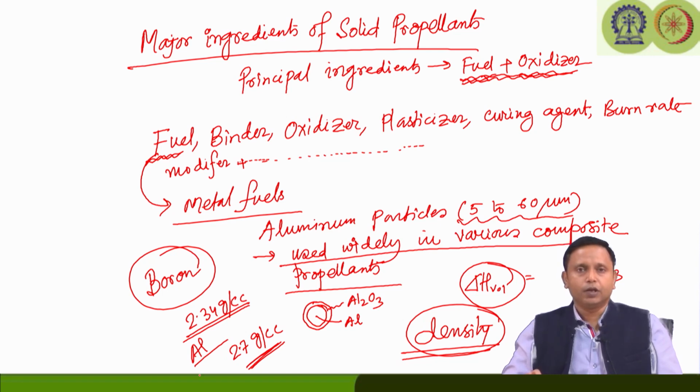The typical residence time in a high speed propulsion system, the particles will not stay longer than a few milliseconds, maybe on the order of 8 to 10 milliseconds. But within that amount of time, the complete combustion of boron and the full energy release is somehow not achievable. So, even though boron is a prime choice in terms of the metallic fuel, it is still not achieved because of the issues with ignition and combustion process.